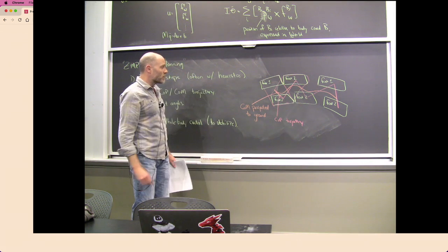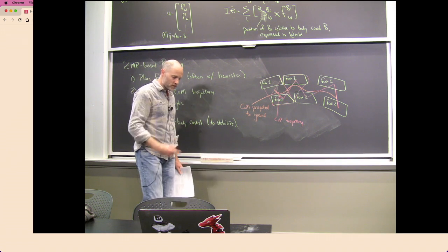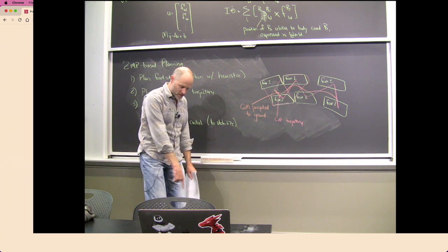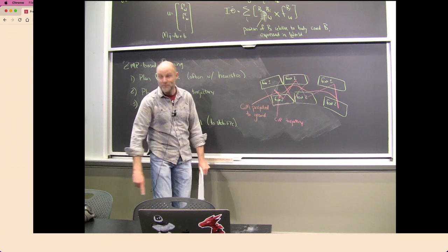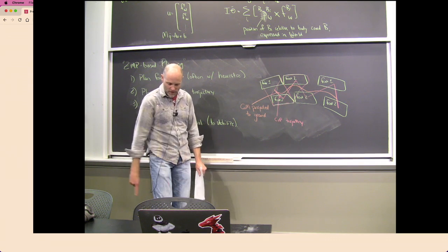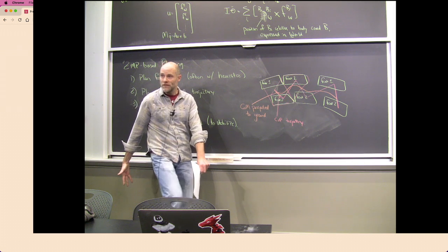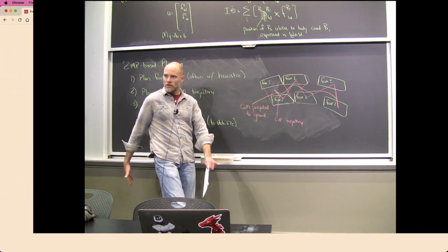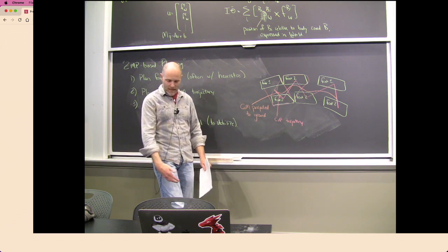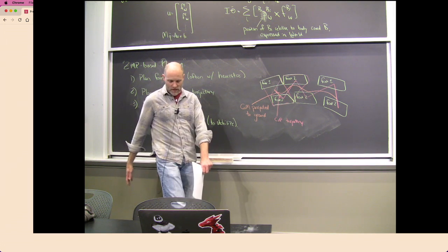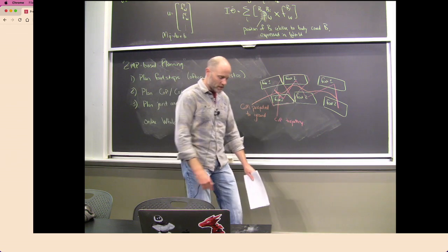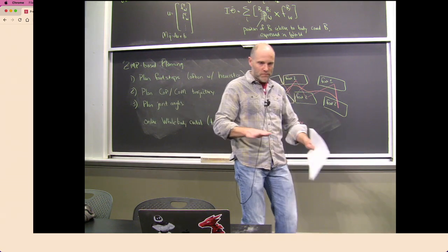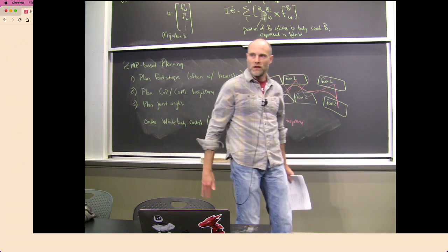Yeah, good. So the original simple footstep planners were really like, I've got some kind of potentially convex region around my current foot position that I would safely move, and I'm allowed to pick anything in that region, sort of ignoring all the details of my dynamics, of my kinematics, and everything like this, in order to make progress towards my goal. So pick the best point in that region to move forward. Very simple, just thinking about feet moving along.